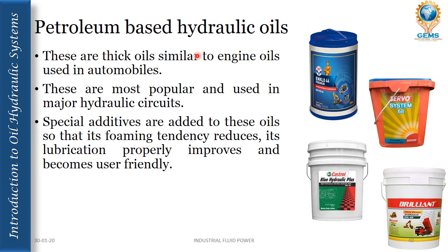Petroleum-based hydraulic oils. These are thick oils similar to engine oils used in automobiles. These are the most popular and used in major hydraulic circuits. Special additives are added to these oils so that their foaming tendency reduces, their lubrication properties improve and they become user friendly.